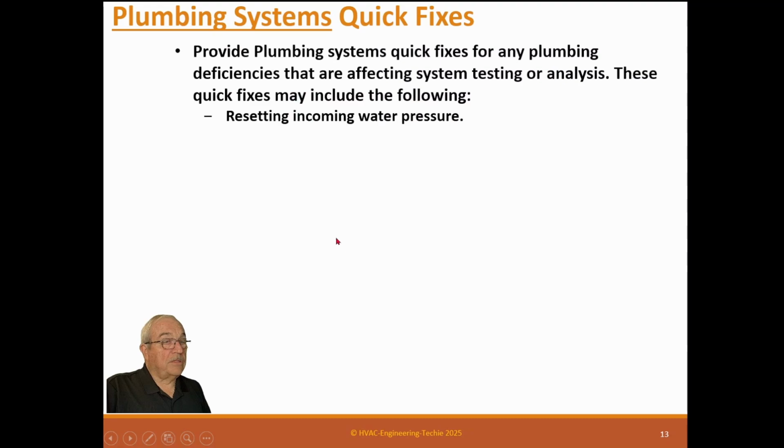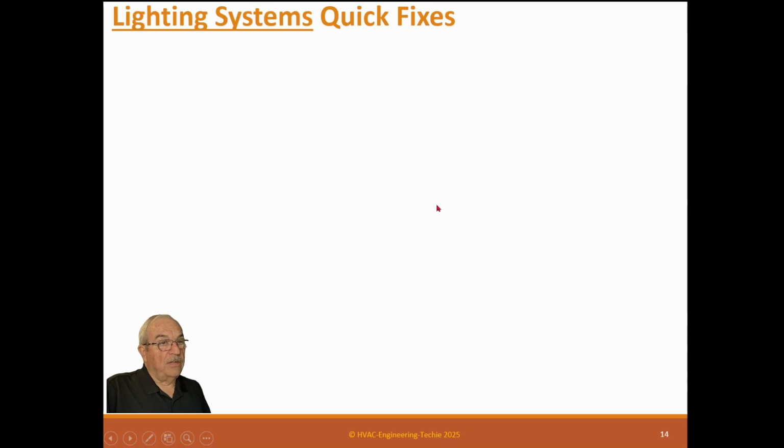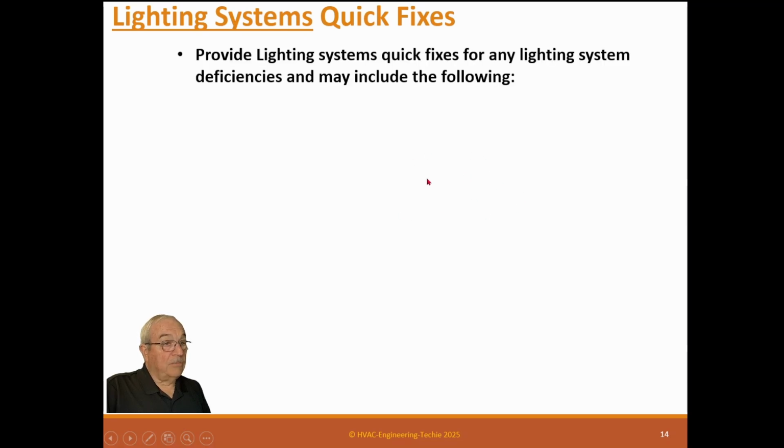Plumbing system quick fixes. Resetting incoming water pressure, adjusting water pressure boosters, adjusting hot water temperatures, correcting system or fixture leaks, adjusting flush valve flows. Those are things that help plumbing.